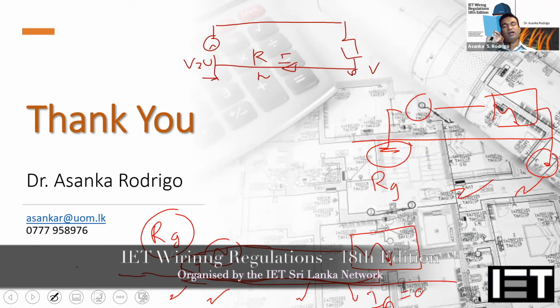So the best thing is, if you can do the balancing and reduce this neutral current, you can reduce the neutral voltage as much as possible. In a TN system, the easiest thing is that you can earth this point. If you earth this point, then obviously the voltage here is 0. You can maintain the neutral point voltage at 0, but in the TT system this is not allowed, because you cannot have a different type of neutral point earthing other than the utility earthing. So this is an inherent problem with the TT.